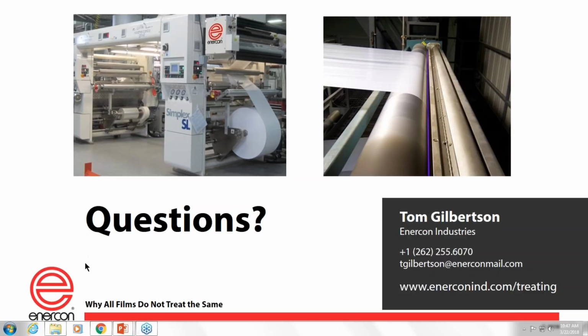You're going to ionize that air, and you're potentially going to get backside treatment. And how you control it is through web tension. You control it through making sure film is flat. On high-speed lines, many times corona treaters have nip rolls and drive systems, which allow us to control the web dynamics as it goes through the treater, thereby controlling things like backside treatment.